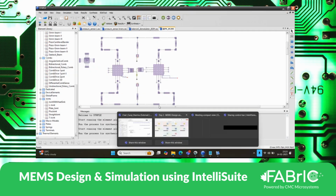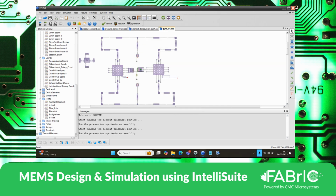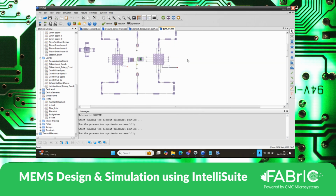I think the other way around would be easy if you just do the schematic, the number of capacitors like comb drives, to get the required capacitance value, and then adjust that into your GDS.